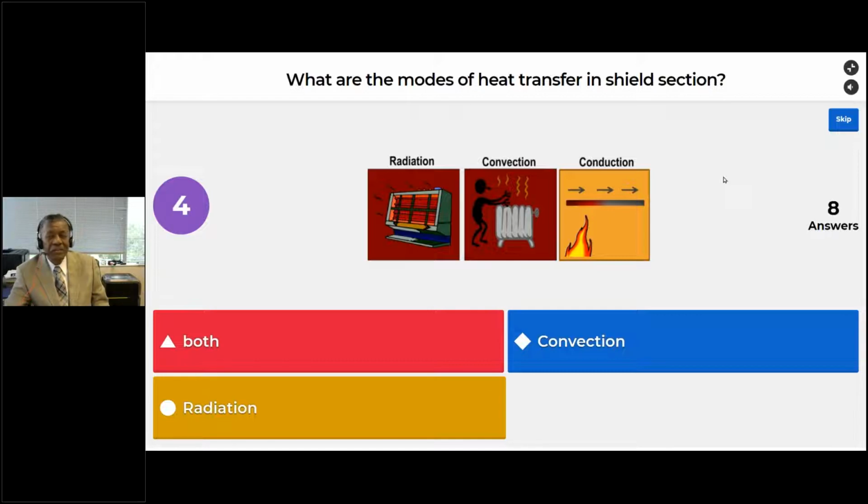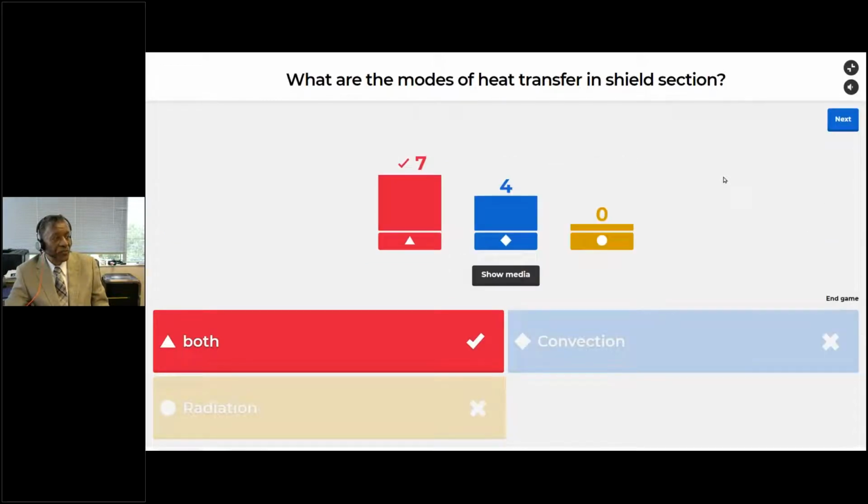That's where the maximum heat flux or maximum heat transfer rate is experienced. It's basically where both radiation and convection heat transfer is taking place. So it's a very, very critical section. And a lot of times it has high tube metal temperatures. It may have coking. It may have tube ruptures. It happens pretty often.